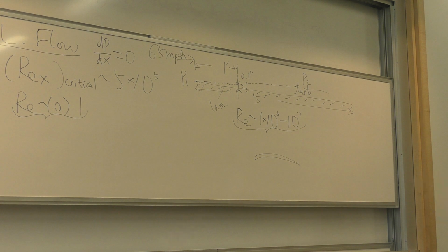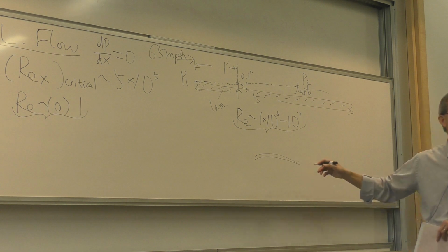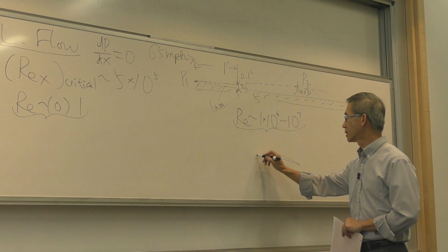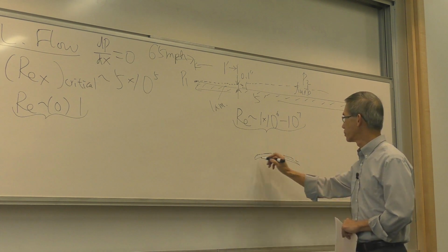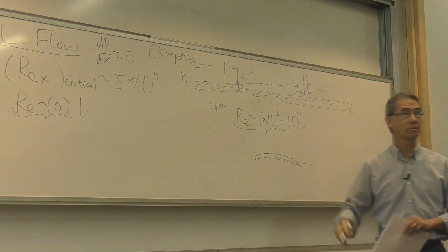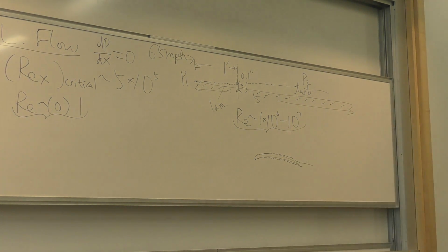For a large object like a ship or an automobile at very reasonable speed, the Reynolds number is very large. So that's 99% of our engineering problem that you pay to solve. For that, this boundary layer concept is very clear and applicable, and it creates this invisible shear layer. Within that dash line, viscous effect is dominant, as important as the inertia effect.